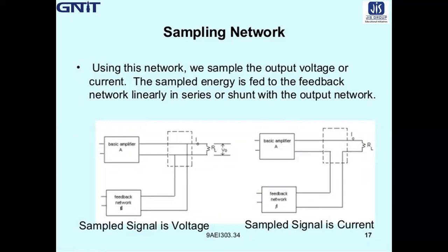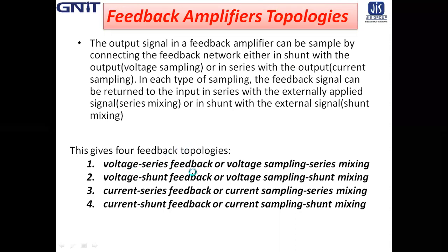These topologies are basically voltage series feedback, or voltage sampling series mixing; voltage shunt feedback, voltage sampling shunt mixing; current series feedback, current sampling series mixing; current shunt feedback, current sampling shunt mixing.